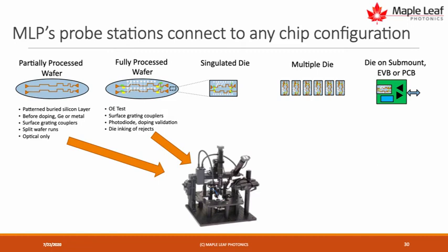Once you have a singulated die, you have more control. It's a more realistic environment. You can bring in the full OE tests and bring drivers up close to the chip and so forth if you're running at high frequencies. You often work in this environment to develop further your tests that you want to implement for either device qualification or for full RF testing.